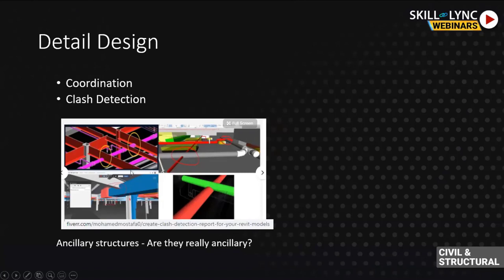I'll prefer the holes in the midsection if it's simply supported, because the shear is not there and the web doesn't have to take the shear, so I can accommodate this pipe here. If I know this early on, I can move it. If it goes to site like this and it's not well coordinated, site can put a hole in this on the basis of the drawing from MEP, and then it's a problem.